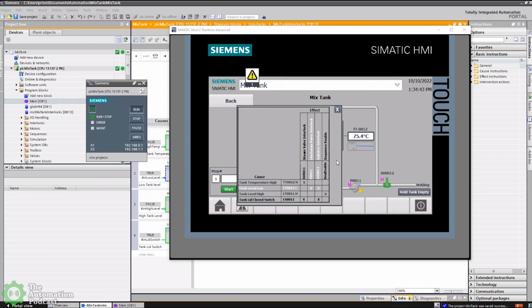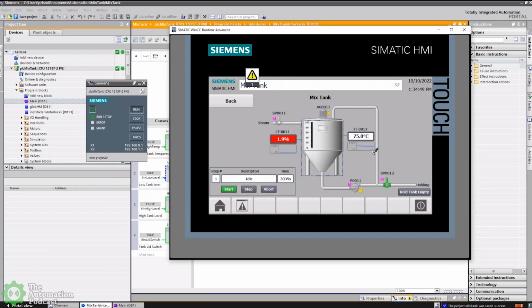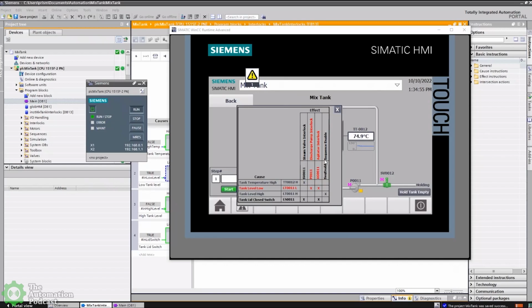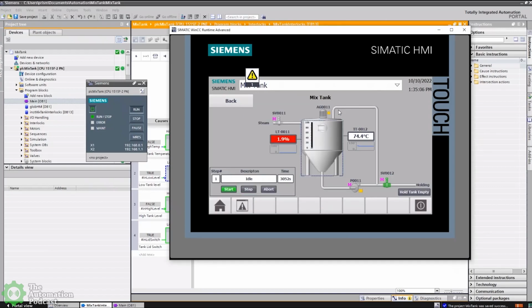Nice. The cause and effect matrix provides all these tags and statuses, and that's what Ron mapped to a pop-up. Eventually, one day, once we have our unified HMIs launched, it'd be ideal to have some standard interfaces that bring up the cause and effect matrix directly from the PLC. But right now, Ron just pulled the status bits out of the data block. Or even the code view in the HMIs. If we could do a code view with a cause and effect, that's on my wish list. That's on my list too. That would really be awesome.